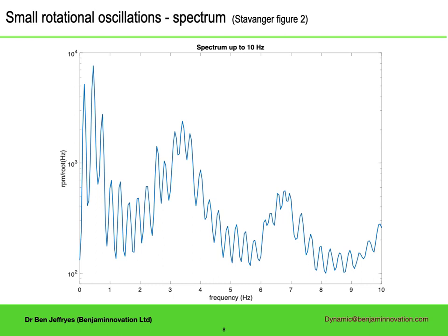Theoretically, the lowest resonance is close to a quarter wavelength resonance for rotational waves, and the higher ones multiples of half a wavelength greater. So the second is at 3/4 of a wavelength, third at 5/4, etc. And by eye, this is borne out by the data. There's a secondary periodic structure here, with an enhanced response to about 3.5 Hz and multiples, and this probably comes from the drillstring structure. There is heavyweight pipe above the bit and the BHA.